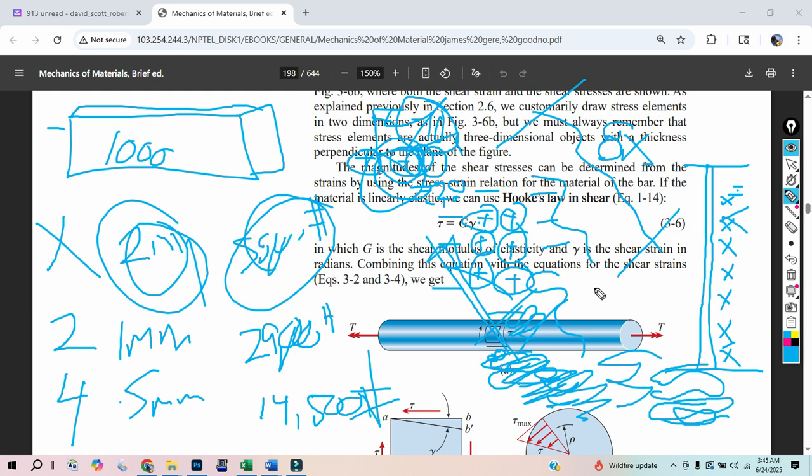But what we find is that through the strength of a material, from having it and then doing what we want with it, it's a linear process. So I would just suspect, and the literature says, like the very basic Google AI says, the linear process is just a slight restructuring of, not restructuring, because after you get past that linear range, you get into plastic range, and that's permanent deformation.